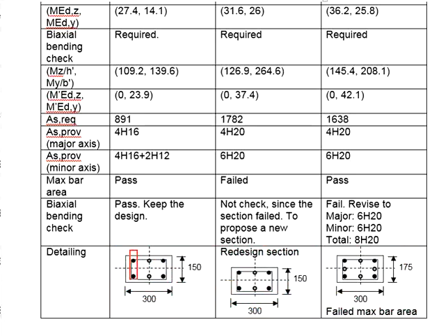For H16, it will be this, plus 2H12. If you are talking about the minor axis, you will have 6 units of reinforcement bar to be effective. However, if you're considering from the major axis, the 2H12 here is at the neutral axis. These 2 bars will not be effective for the major axis. That's why, as far as the major axis is concerned, only 4H16 is provided.